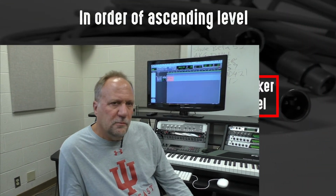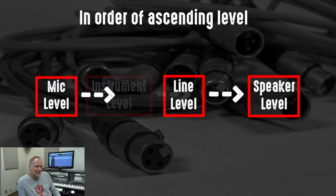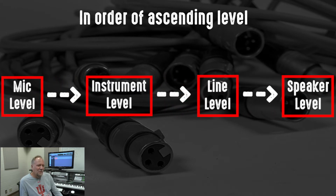So you get an idea: you've increased this signal probably 10,000 times beyond what it originally was when it came out of the microphone. It takes some pretty sophisticated electronics to do that, and you can't do it all in one step. Now, in addition to microphone level and line level, in the middle there is something that's called instrument level.